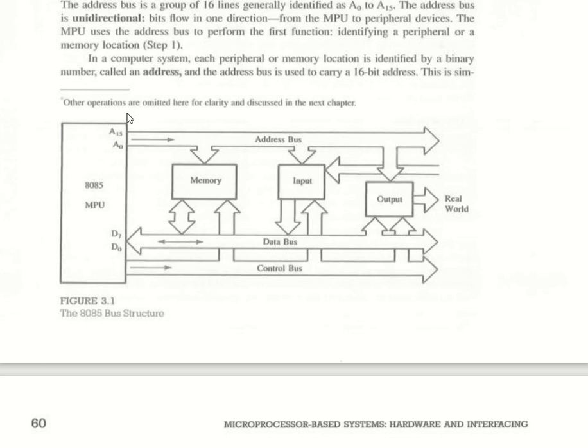We will be seeing the pin diagram of it in probably the next class. But for now, know that the pin arrangement from A0 to A15 stands for the address bus of the microprocessor, and the pin arrangement of D0 to D7 stands for the data bus. Then there is a control bus going separately, but that's a discussion for some other day, though I will provide a little bit of a glance.